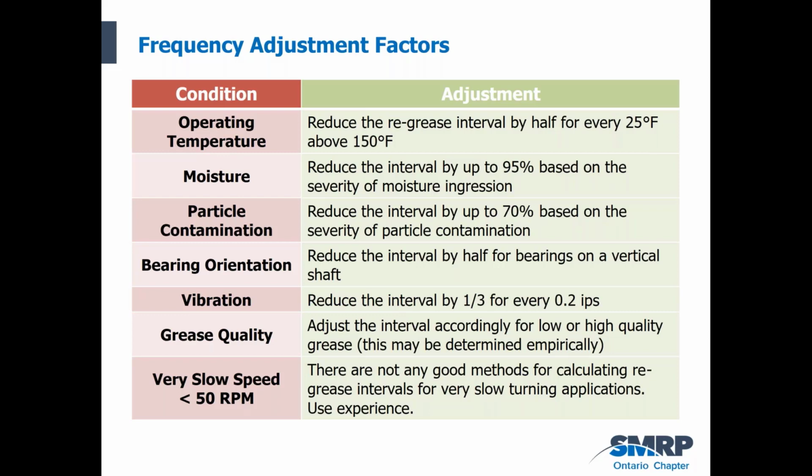It's going to allow the grease to fall out of that bearing. So for a vertically mounted shaft, we will regrease that bearing more frequently. A good example would be a water intake pump. If the machine is vibrating, I don't mean that there is a vibration analysis problem, but if it's something like a vibratory screen or something that has natural vibration, that's going to create shearing force within the grease. So we grease more frequently.